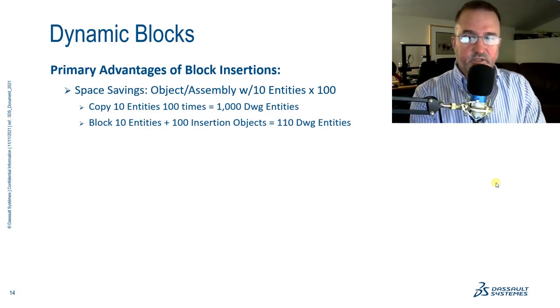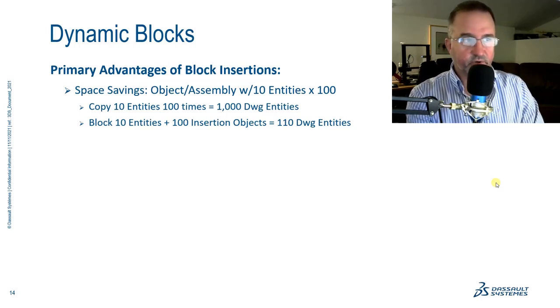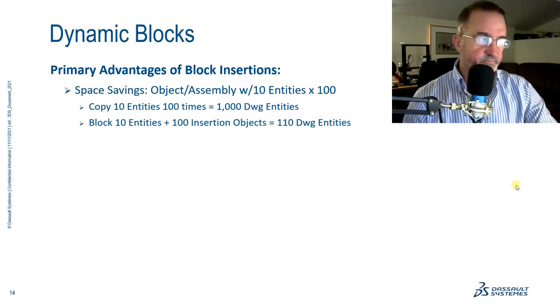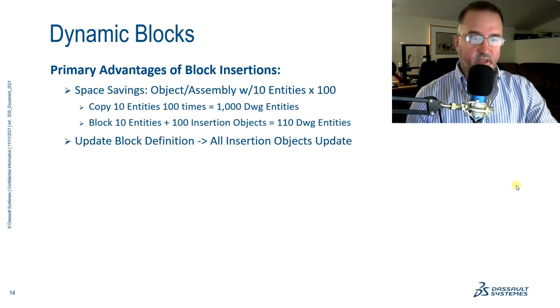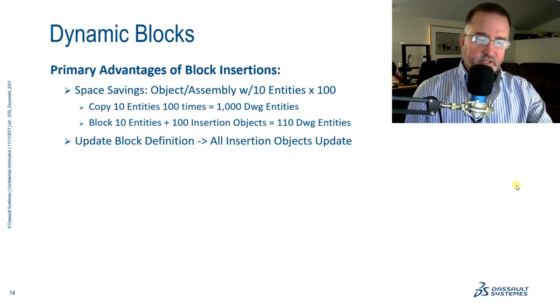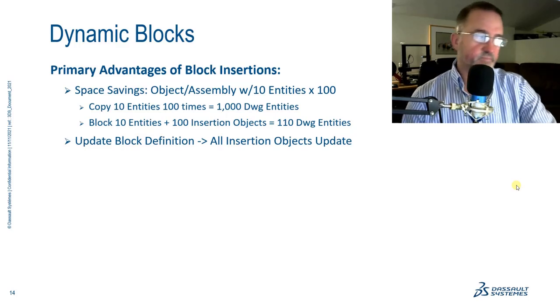So the difference is dramatic, especially when we start looking at drawings that have literally thousands and thousands of components. The savings and the speed and the efficiency of the drawing can be drastically affected by how we use or don't use blocks, especially when it comes into very, very busy drawings. Now, the other advantage to a block is, let's say, just like I talked in the last example, I had to update or wanted to update the block version in the drawing. Simply by redefining that block, I can update every single insertion of that block at one time. So simple update, all the blocks will reflect that update across the board.